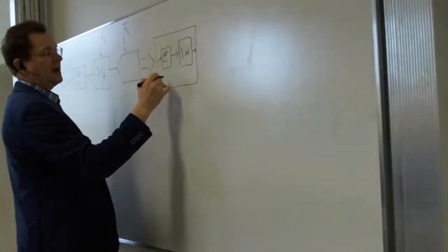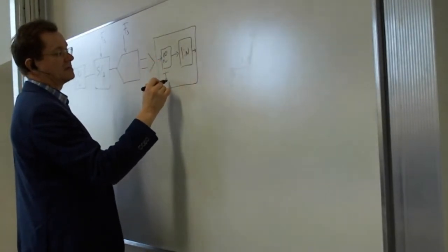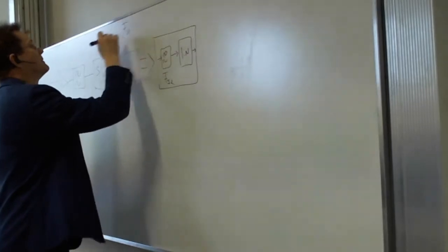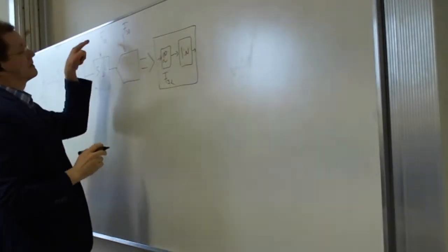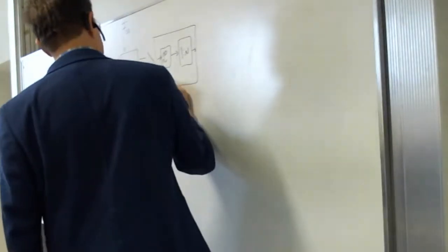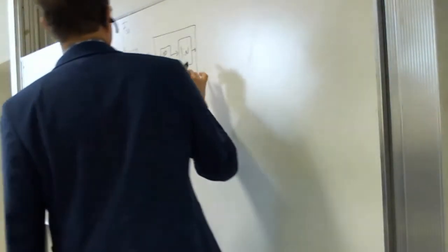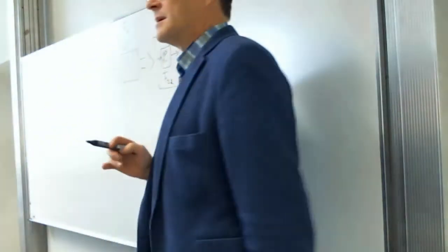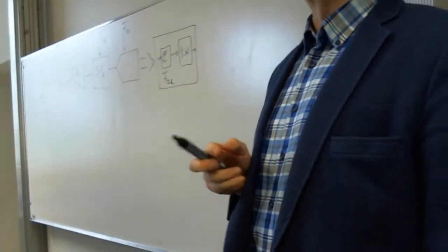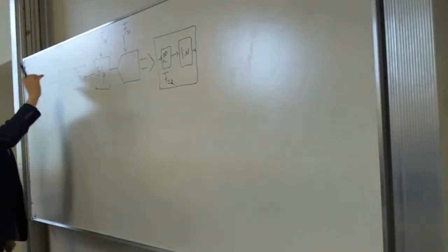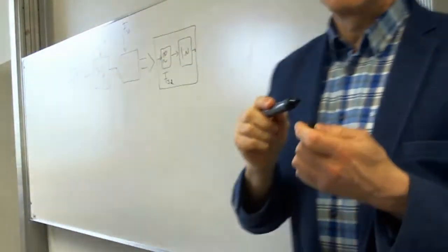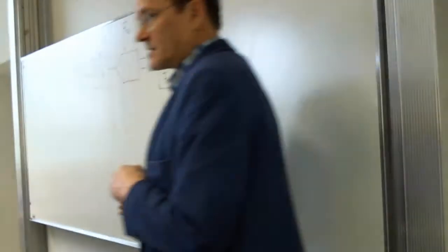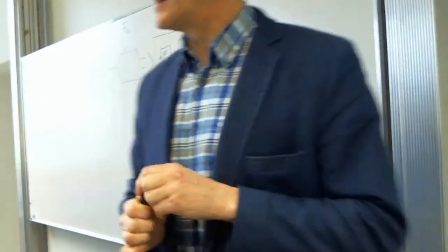And whatever comes out comes out. And here we have a different sample clock. So here we have the primary sample rate, FS1, and then we have this secondary sampling rate. Actually, this is downsampling the data. Downsampling because it basically then reduces more noise. It's better actually to oversample the data and then do some averaging, and then you may actually have better results, well, less noisy at least.